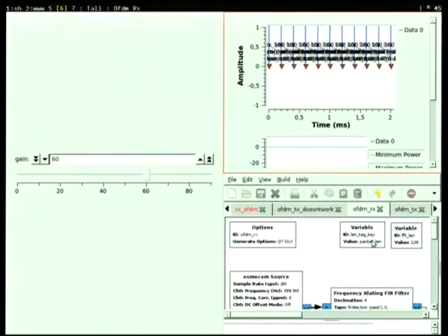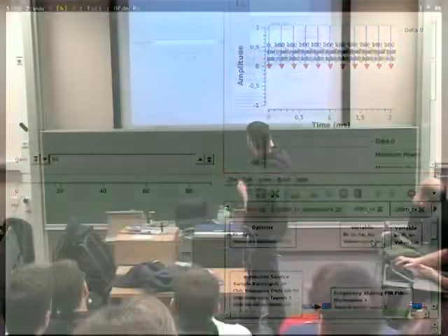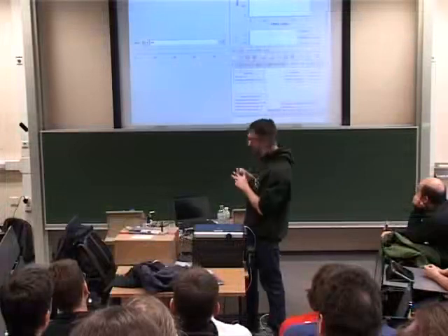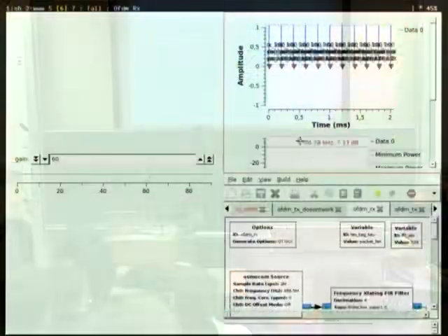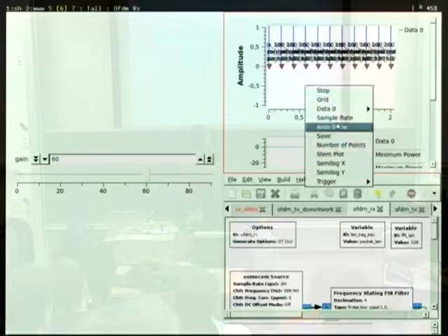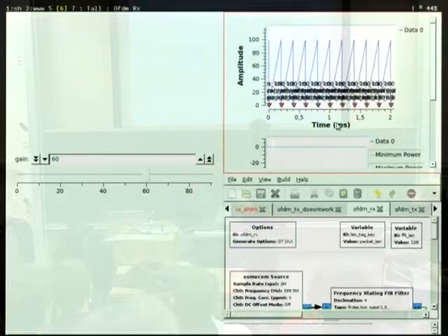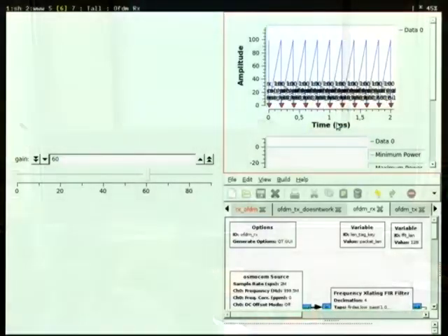Here you can see all these tags. This is from the receive side, so I'm actually receiving packets now. The payload I was sending was a ramp signal, so this is just some nonsense. Sometimes it's useful to transmit a payload that you can plot just to make sure you're getting the right thing. So this is the actual receiver working fine.